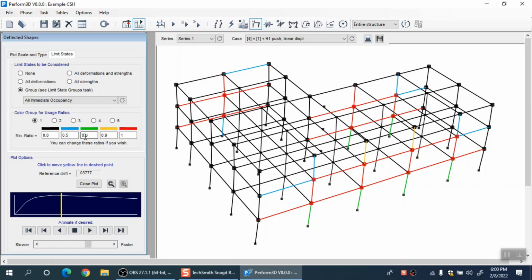I will share one document in which I will show you how I myself show the results of a nonlinear dynamic analysis or static analysis. So, these numbers can give us a qualitative idea about the damage. For example, red color means that this element has crossed IO already, this is understandable.